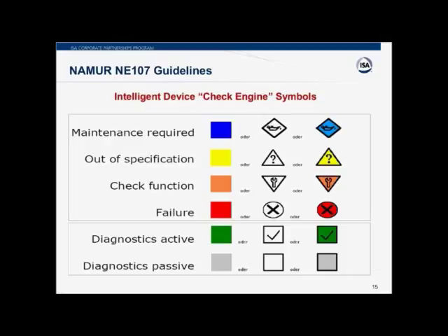The next one is out of specification, which means that, hey, you told me that I should expect to operate in this range or under these types of conditions, but I'm still working or functioning, but I'm now outside those limits. So a real simple way would be, you told me that my calibration range is 0 to 100. I'm now reading 105. What should I do?